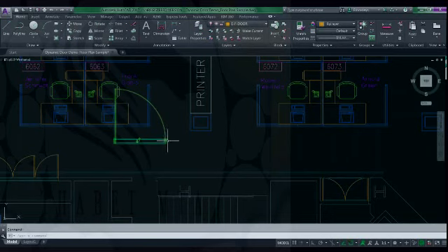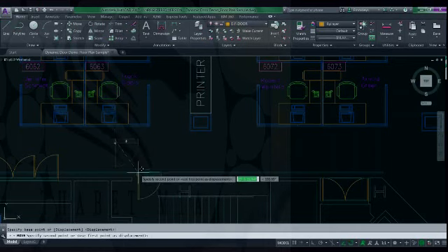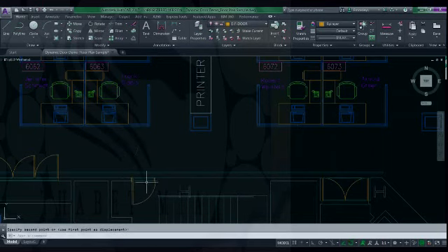As you can tell, it's resized kind of crazy here, and I have different impact areas that I set up with parameters, and I set dimensions. So I'm going to go ahead and set my door down to a 3 by 8, and then I have another grip here where I can flip my door into the room. Let's actually move this down here, and then I have another impact zone where I can flip my door swing to look like that. That's my dynamic block, and then I also can show you my 3 different set dimensions that I have for my door.